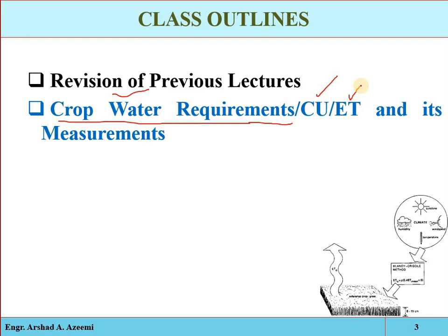The water requirement of a specific crop at a given season is most important in the design, planning and management of any irrigation structure, and each and every crop has a different water requirement, and also the yield of the same crop at different moisture content availability in the root zone is different.